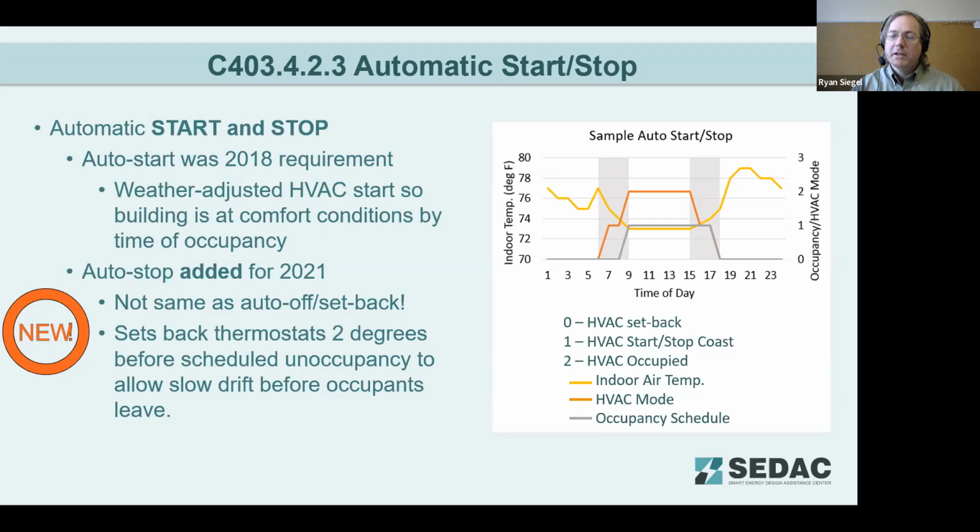We want to make sure the building is ready when the occupants arrive, but we don't necessarily need to bring the system online the same amount of time beforehand every day. So obviously during the winter and summer, when I'm likely to have drifted and it's going to be a little harder to recover, I'm going to want to start those systems earlier. And as I get more temperate times, I don't have to start it as early.